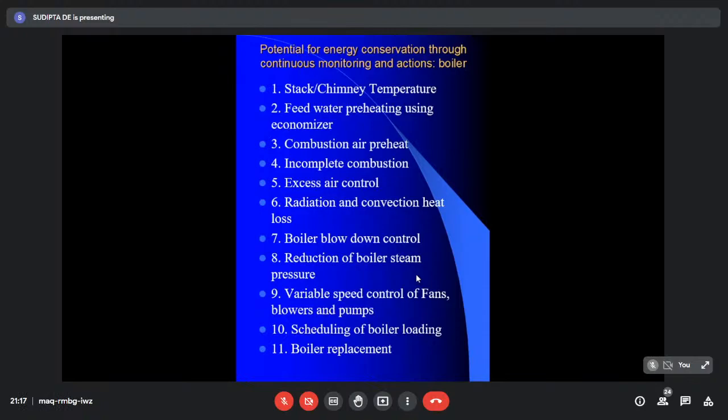There are two ways of doing this. One is keeping your speed constant, but bypassing some amount of the air or water delivered to some other chambers. Energy consumption by the device remains the same; you are only adjusting for the reduced demand by bypassing the main feeder line.